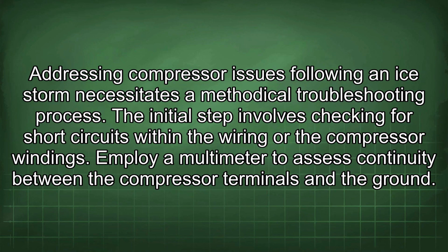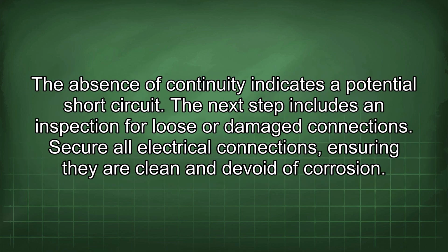Addressing compressor issues following an ice storm necessitates a methodical troubleshooting process. The initial step involves checking for short circuits within the wiring or the compressor windings. Employ a multimeter to assess continuity between the compressor terminals and the ground. The absence of continuity indicates a potential short circuit.